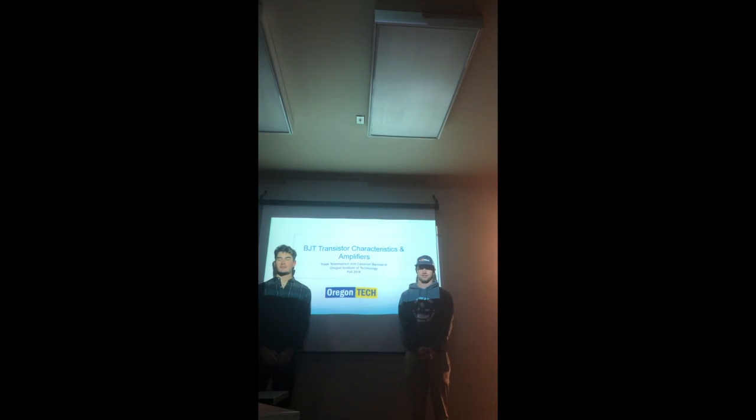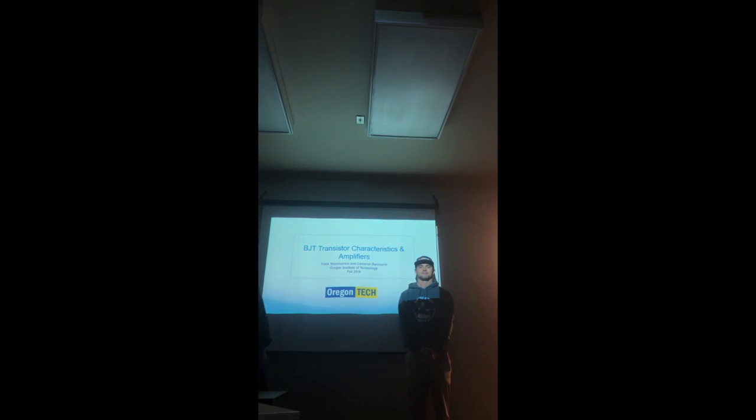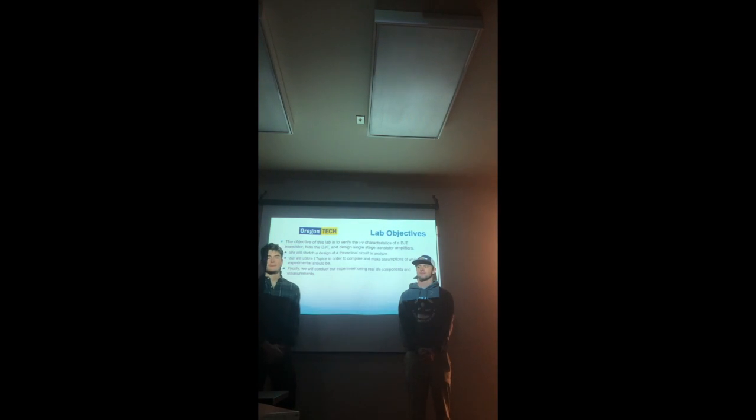We're going to talk about BJT transistor characteristics and amplifiers. So the main objective of the lab is to verify the IV characteristics of a BJT transistor, bias the BJT, and design a single-stage transistor amplifier. We will sketch and design a common emitter amplifier with a gain of -10 and also with a quiescent current of 1 milliamp using a BJT.